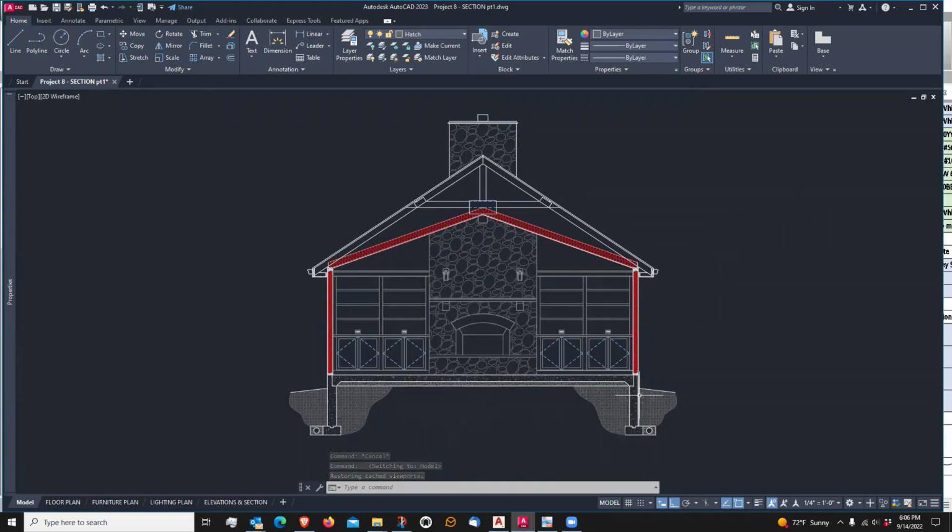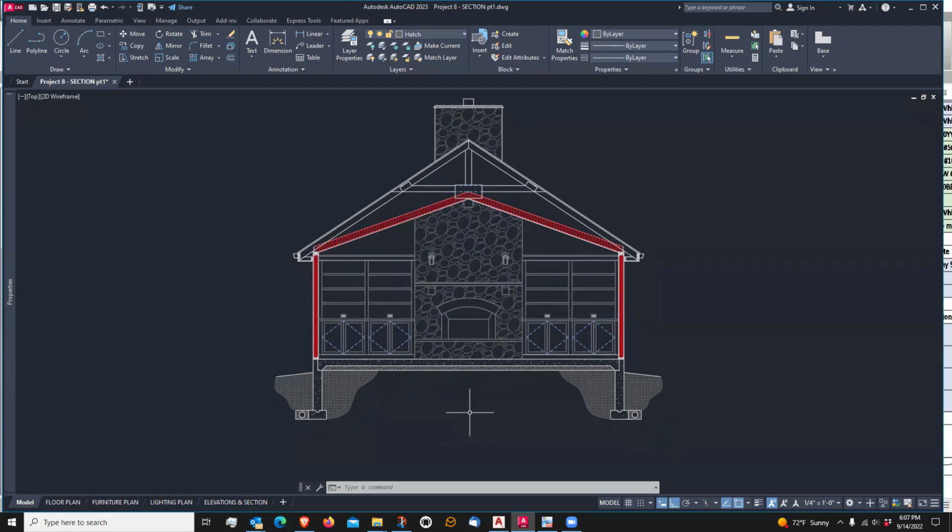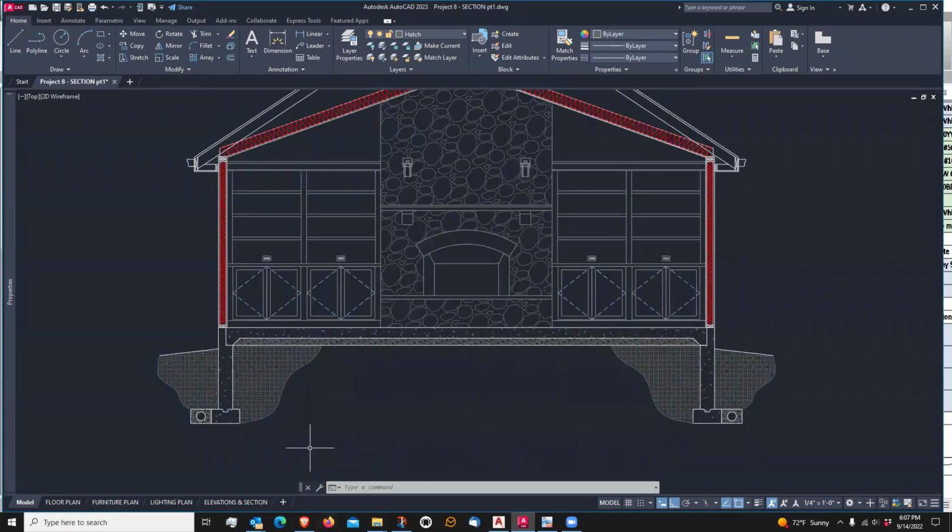So if I go back to our section here, I am showing the foundation coming down here, and this is where it cuts through wherever our building section is. But I'm going to see also the foundation wall down here behind, underneath the fireplace, and we're going to see that in a dashed line. So I'm just going to draw dashed lines.